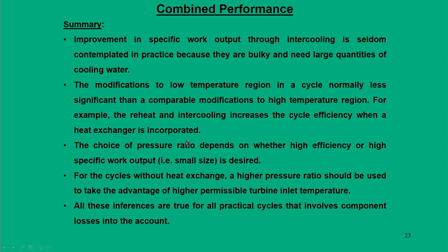But there are some situations where the choice of pressure ratio is very vital, and it depends on whether high efficiency or high work output is required. That means, high specific work output means you require a small size unit, so you need to decide whether you require a small size unit or a large size unit. So, depending on the pressure ratio we can make a judgment.